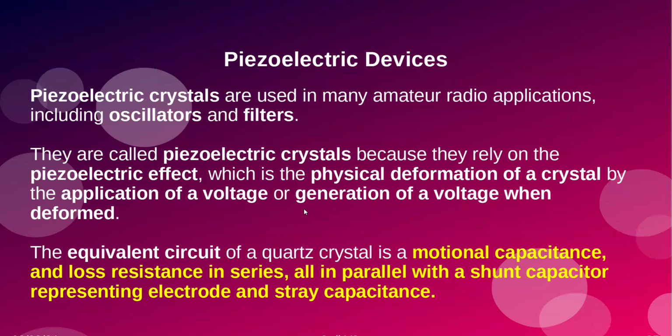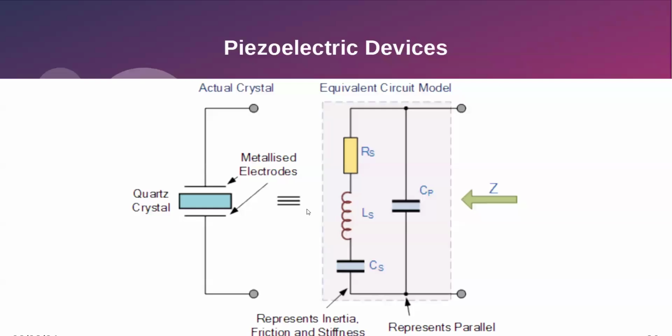The fact that it is flexible and that it does flex, and then it has mass. So we'll see over here what they describe. You've got series resistance, motional capacitance, some inductance, and this shunt capacitor. I point that out. It's a test question. Remember, it'd be the only one with motional capacitance. Yeah.